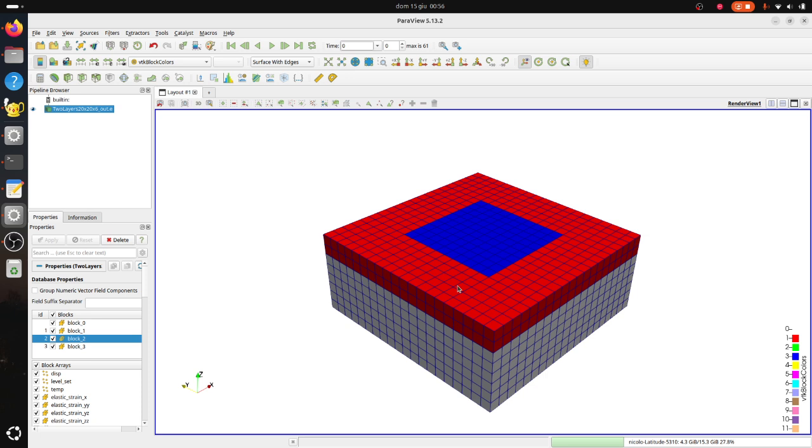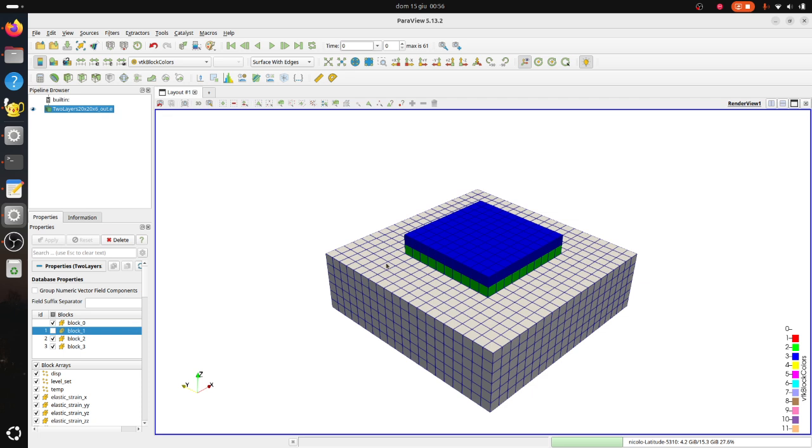However, when I run the simulation, because this is a thermomechanical simulation, what I want to do is to simulate this region, the top part of the white block, as a boundary which can, for instance, have a radiative loss. So I need to be able to apply a boundary condition to this top. So I need to create a surface, because otherwise the generated mesh generator does not do that automatically.